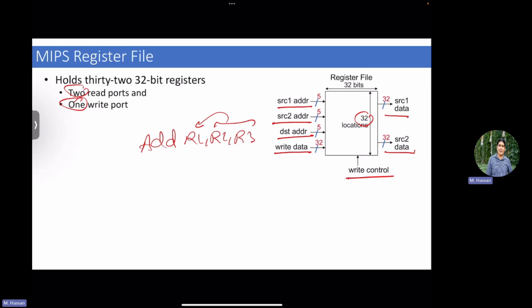And this takes us again to Amdahl's law, or even the general rule of computer architecture: you make the common case fast. Why did I make that choice? Because most instructions have 2 operands, so most instructions will benefit from 2 read ports. So it's a wise decision to make. You trade this area for, again, performance. That is very common. Good. Questions?